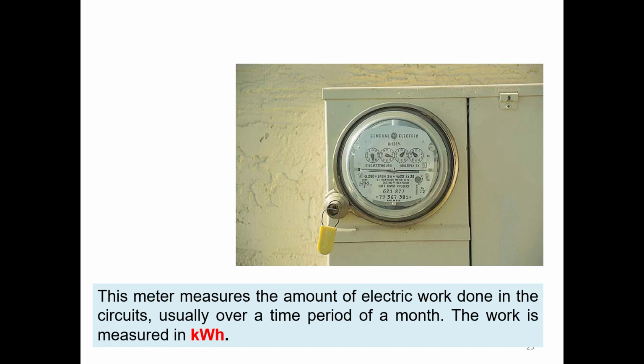Usually the units that appear in our electricity bills are kilowatt-hours. This is how much energy we consume. And what I want to show you is this unit corresponds to units of energy. And usually this is the unit that appears in the electricity bill. And let's write this. Then we know kilo corresponds to 1,000. And let me write here 1,000. We know watts correspond to how much work per unit time, meaning joules per second. And also we know in 1 hour we have 3,600 seconds. Then we can multiply here by 3,600 seconds. And we can see the seconds cancel out, and finally we had the answer in joules.